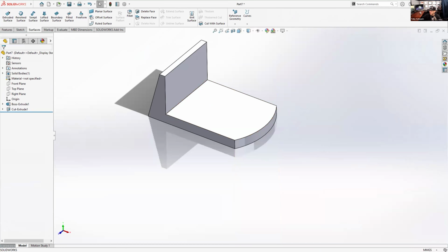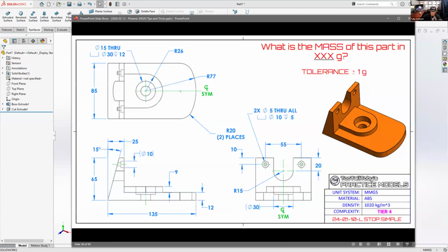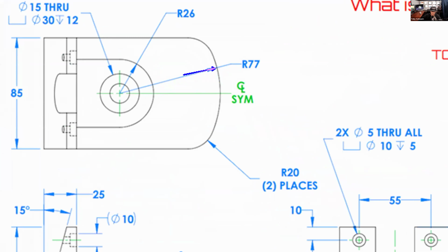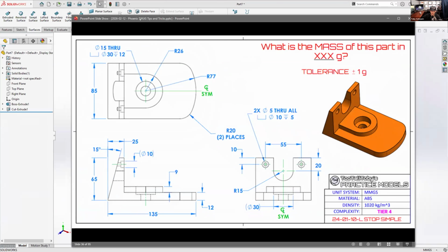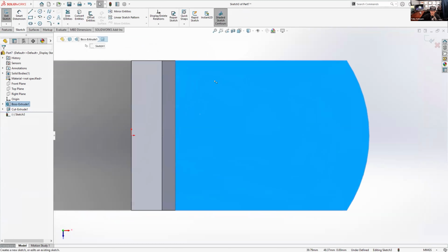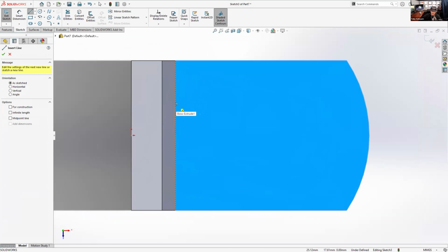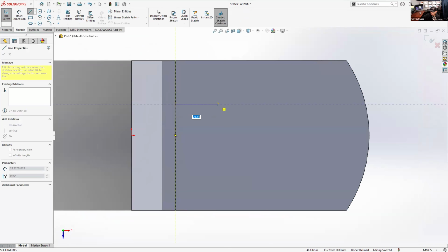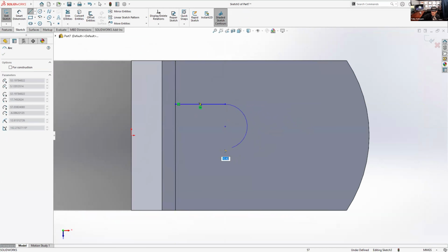And now I think we're ready to create this shape here. It's got a concentric relationship essentially. So that radius 77 has a concentric there for that tombstone shape. Let's see if we can do some auto dimensioning. Pick this face, begin a sketch, orient our view, S key, line, single click, move our mouse, single click again, move our mouse away, come back, touch the endpoint, come around here. This is going to have a radius of 26, enter. Oops. There we go. 26.